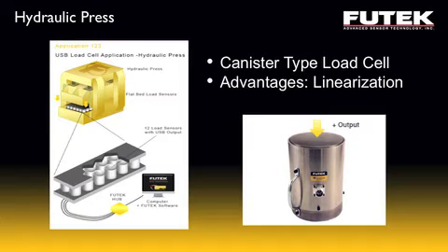Now, some customers don't have room for load cells in place, so they have to monitor the hydraulic line pressure and then convert that to load. The role of the software here is key, given the right tools to make those measurements possible.